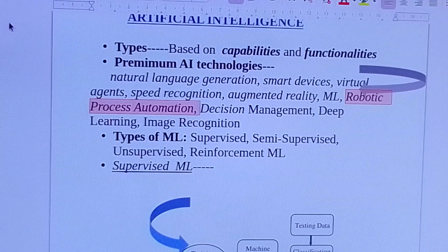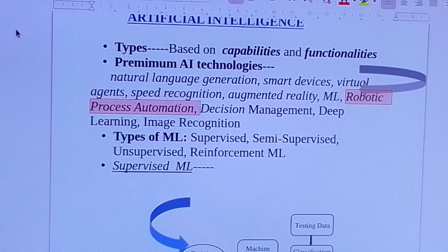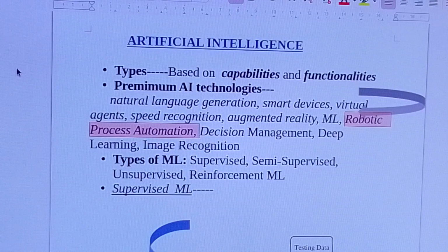In a drum controller, as the drum rotates, it actuates the switches which are wired to hydraulic or pneumatic valves. Thus, the manipulator movements are controlled by the rotation or the advancement of the drum. It is now obsolete. An air logic controller employs a number of pneumatic valves which in turn control the opening and closing of the main valves of the robot manipulator in close synchronization with the timers.